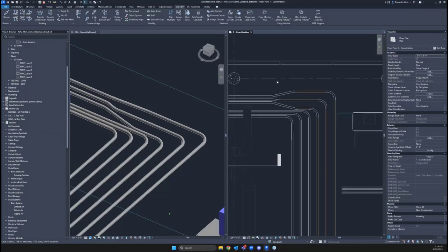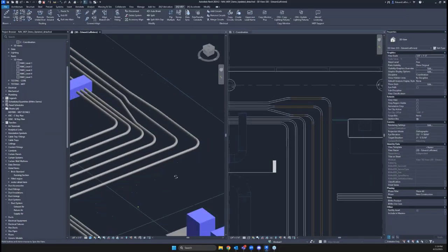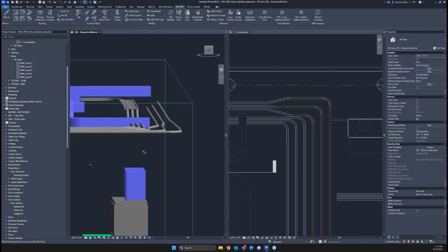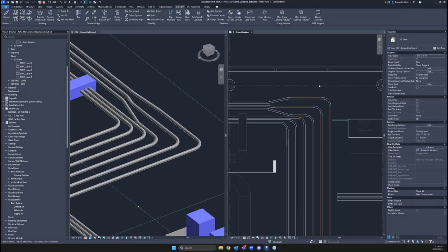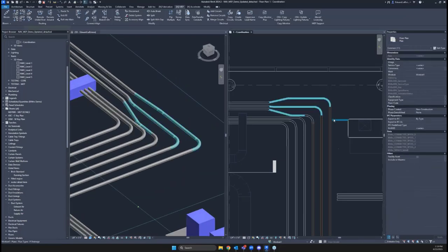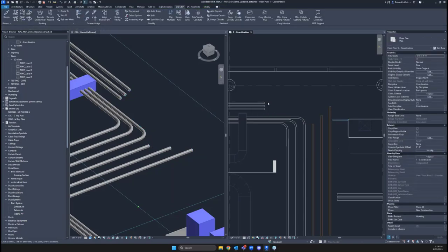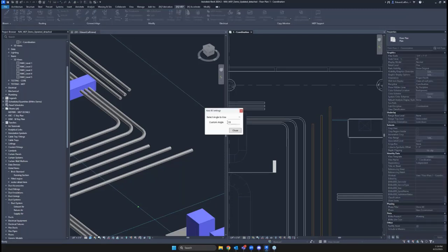Now, I can't hear you guys talking back to me or laughing, but if you route conduit, you probably laughed at that. That was horrible. We don't want to do that. Let's delete it. What I'm actually going to do here is that kind of rolled 90 shape. We're calling a kick 90 here. Let me go ahead and call out maybe a 5-degree bend to go ahead and make that corner.